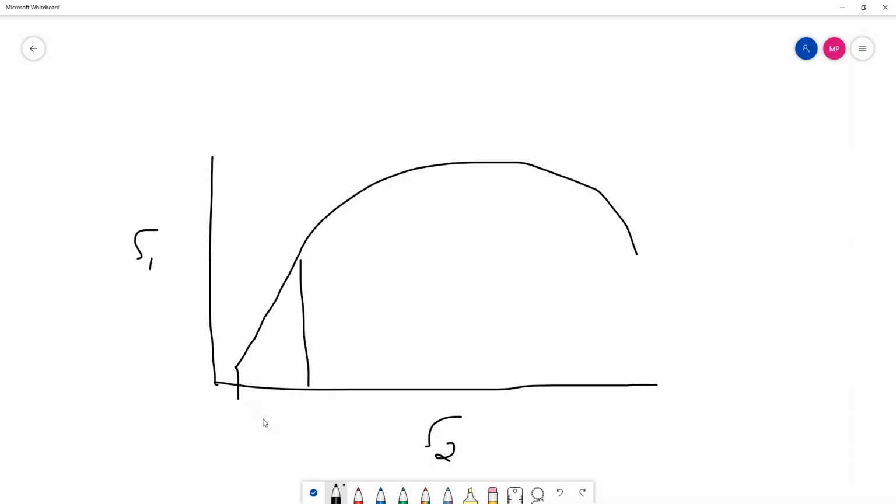If you use the example of a paper clip, when you're bending that paper clip back and forth and you can return it back to its original shape without seeing any kind of bend or any kind of distortion, that's this area here, it's elastic. It just means that it just snaps right back to where it was. After this point, once you've added more forces, you're getting this sort of curve here. This is when you start to see the bend in the paper clip. And this is how cutting materials actually works.